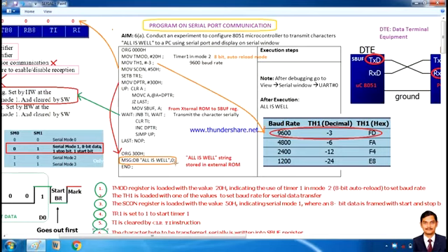Whenever your microcontroller finds a null character with this instruction, it will jump to the last. Till it finds this, you keep on sending the data one by one serially. The data stored externally in this location is initiated with the help of DPTR. MOV DPTR, this is the starting address of the external ROM where I stored the "all is well" information.